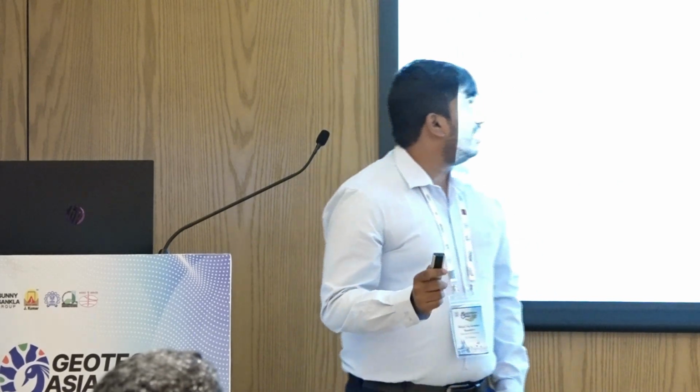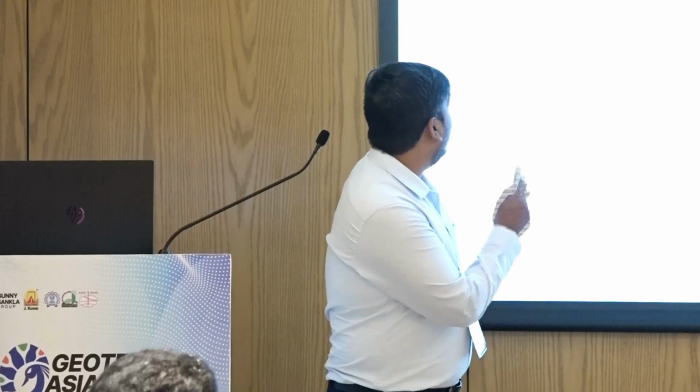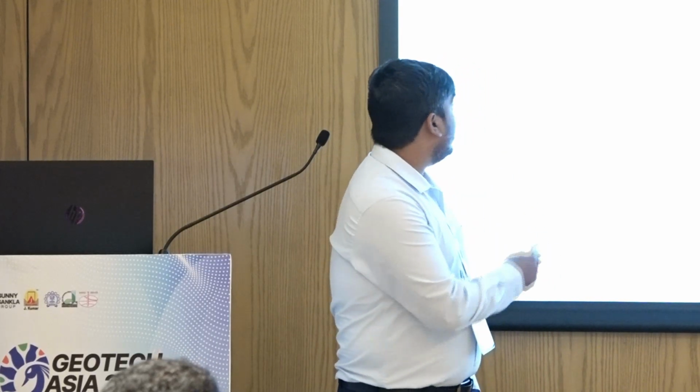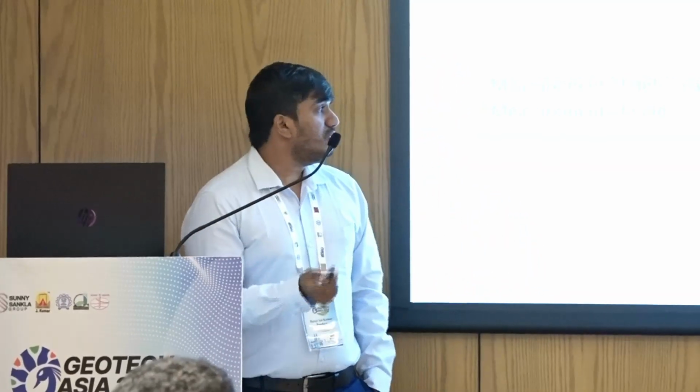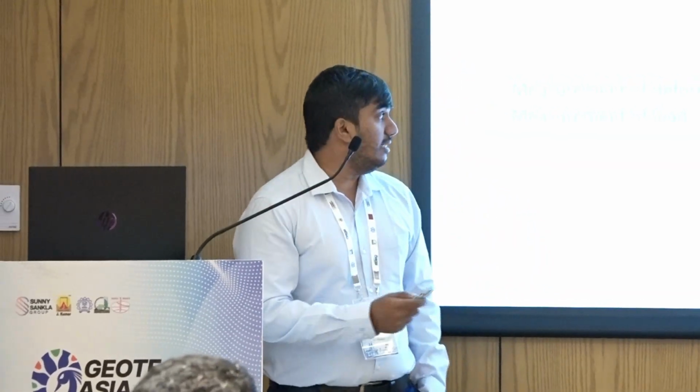Coming to the methodology and data acquisition, the samples were demolded for 20 minutes and destructured. Afterwards, cement slurry at a water to cement ratio of 0.6 was added, and then we poured it in the unstressed sample, and likewise for the stressed sample. The stressed sample was loaded up to 400 kPa. The measurement was done with global LVDTs and an S-beam 20 kilonewton load cell.